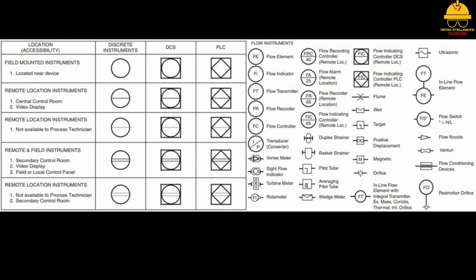High pressure and low pressure sides are located on each side of a pressure capsule. The orifice plate creates an artificial low pressure situation inside the pipe that can be measured and transmitted to a controller. Fluid flow is typically controlled with a flow control loop, FIC. In this system, each of the 5 elements of the control loop will be flow-related and labeled appropriately. It is also possible to have other flow symbols like flow recorders, FRs, high flow alarms, HFAs, and low flow alarms, LFAs.